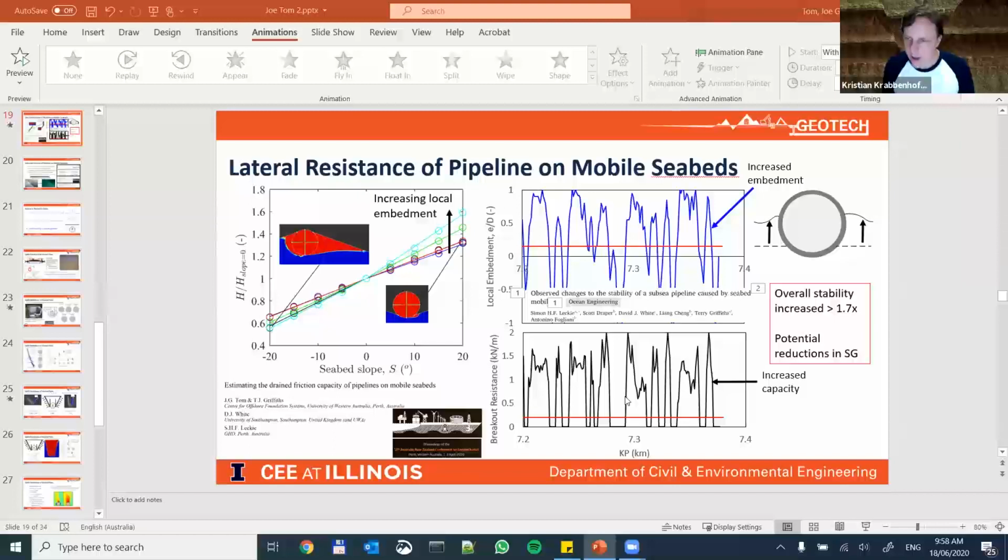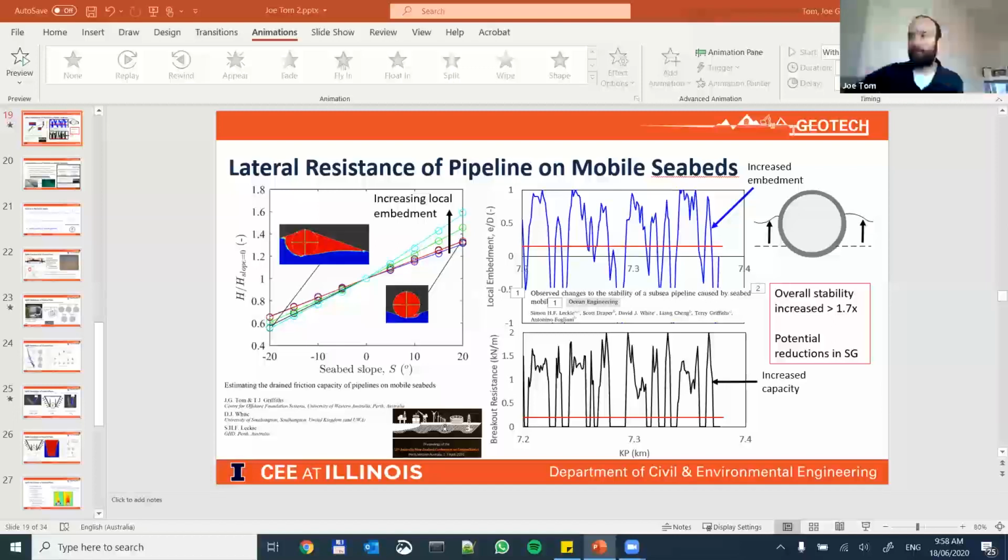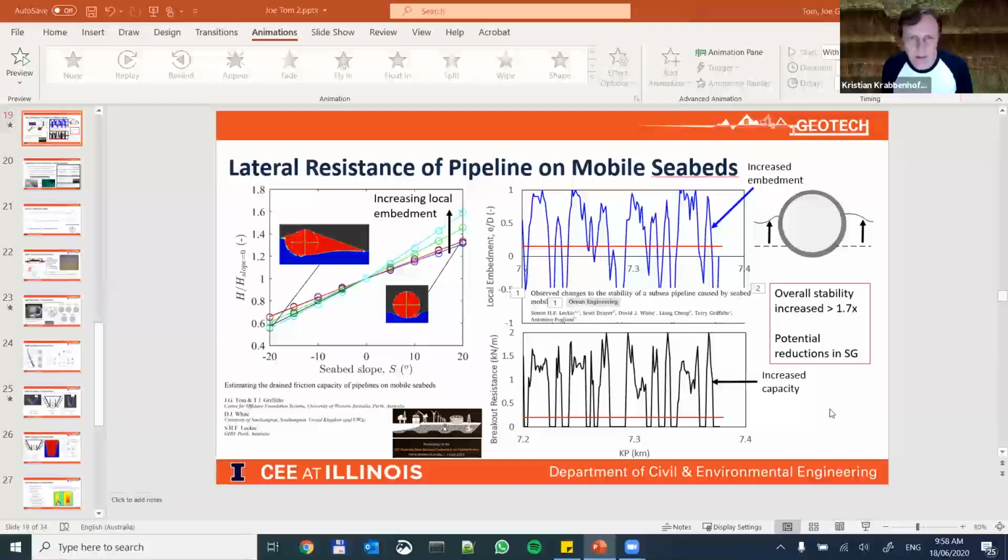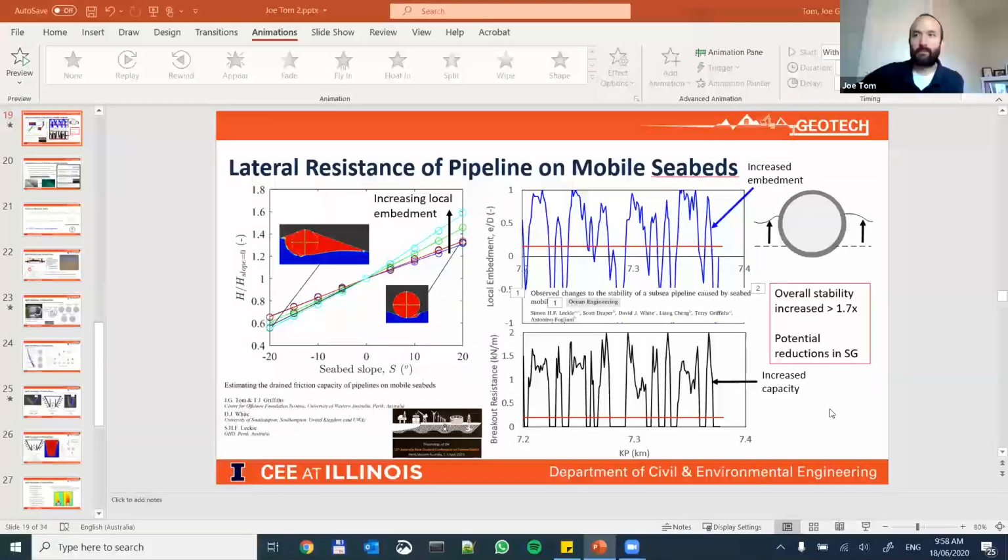Cool. And maybe the very last one has to do with the interface condition. So I'm assuming you've used the standard OPTUM interfaces, so it's frictional contact, and you have the possibility of specifying a roughness. I don't think you can do it in many other ways. You can of course play with that roughness, but there is some friction at that interface.